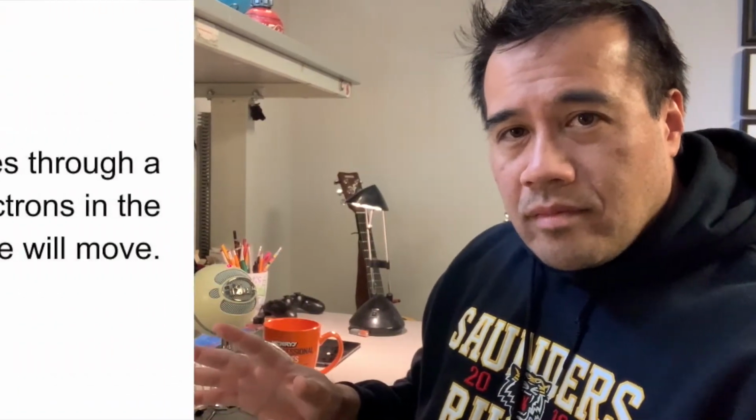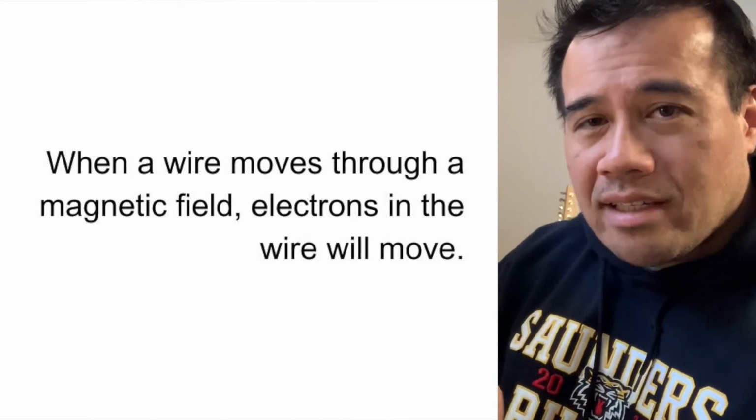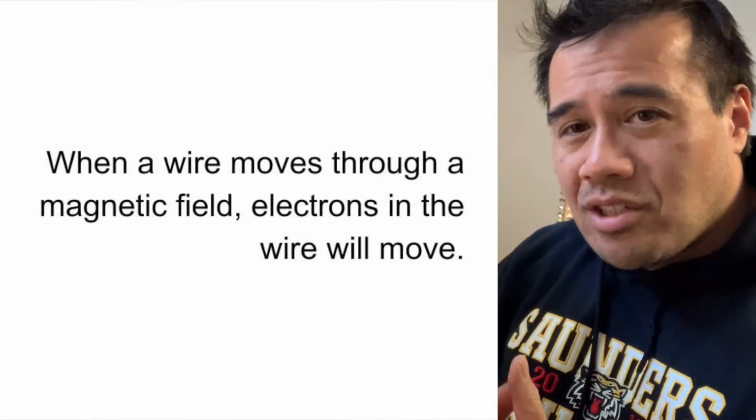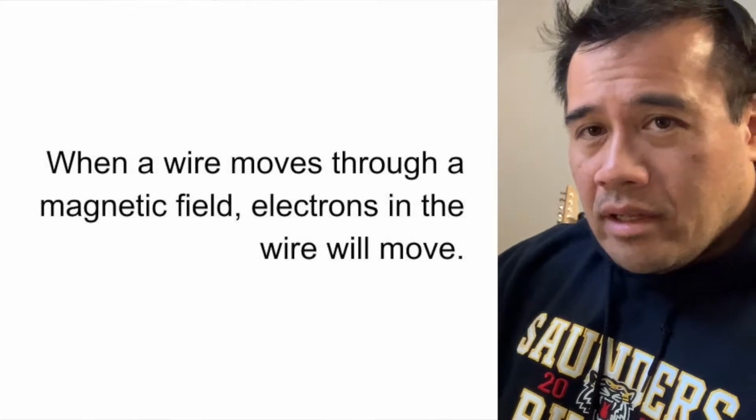So from that quick demo, we know this. If we have a coil of wire and we have a magnet, move either the coil of wire or the magnet past each other, and it will cause the movement of electrons in that coil of wire. It doesn't matter if it's the wire moving or the magnet moving. You just got to have one of those two things moving, so that way you have that magnetic field moving through that coil of wire and you end up having electrons moving.